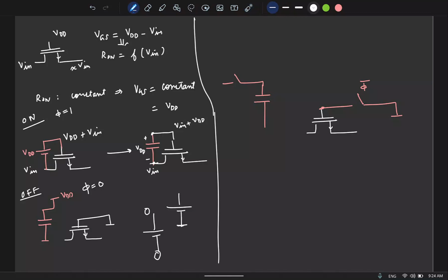So we also have to charge the capacitor to VDD, and I'll do it like this. Again, this should be clocked at phi bar. And when the switch is on, I'll have to put the capacitor across the transistor. So I'll connect it using 2 more switches.